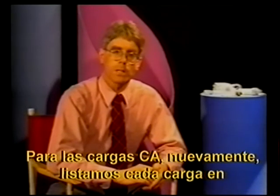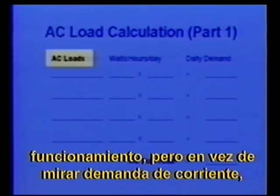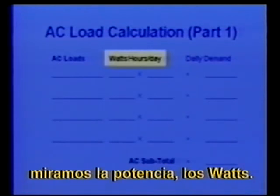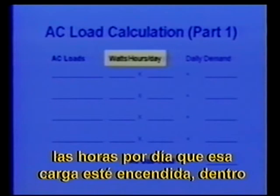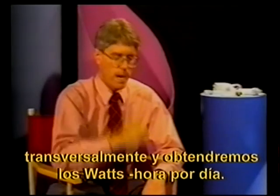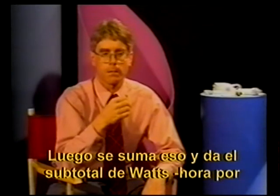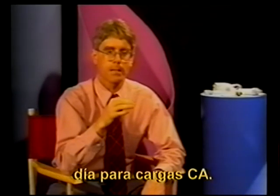For AC loads, again, we list out each load that might be operating, but instead of looking at current demand, we look at power. We look at watts. So indicate the watts that might be drawn, the hours per day within 24 hours that that load might be on, multiply each one of those across to get watt hours per day. And then you add that up, that gives you the subtotal of watt hours per day for AC loads.